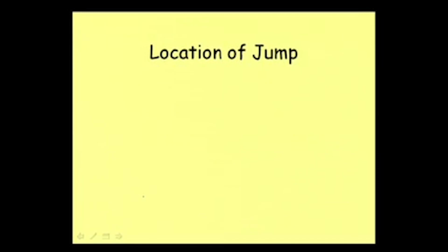Well, then another topic that is of importance is location of hydraulic jump. As we have discussed, location of hydraulic jump, say on the downstream of a dam, where the hydraulic jump will be occurring, that is very important. And if we can control the tailwater depth somehow, suppose it is low, it is getting repelled and the jump is occurring here.